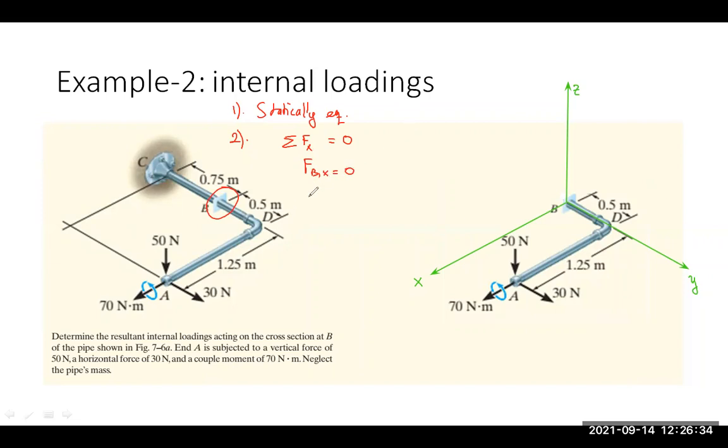Then how about in y direction? Sigma F in y direction. The total must be 0 in order to be in statically equilibrium. Okay? And here we obtain that the external force applied at point A is 30 Newton in y direction.